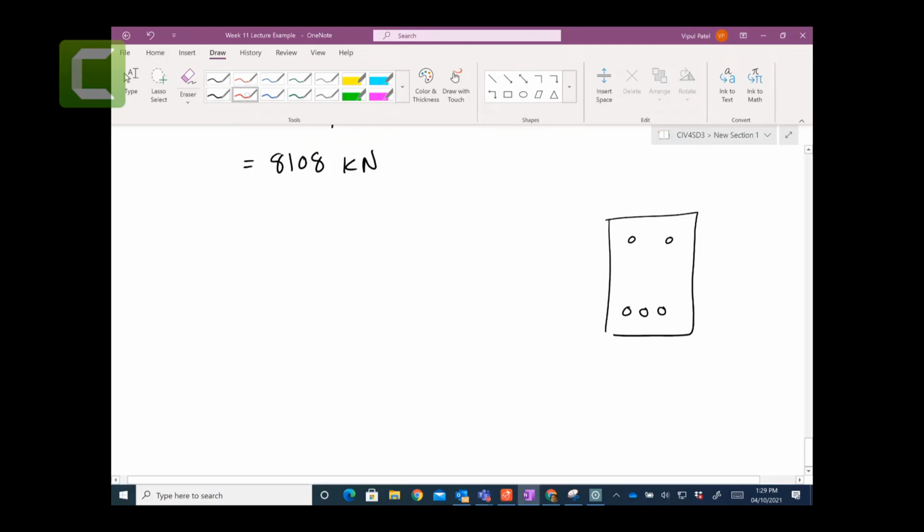So in that case, you need to calculate the plastic centroid, let's say dp. How are you going to calculate dp? dp is equal to the sum of the force times the distance over the sum of the force, meaning that you can calculate the force in here, force in here, force in the concrete, and each distance from the respective reference. So that's how you calculate the plastic centroid dp.